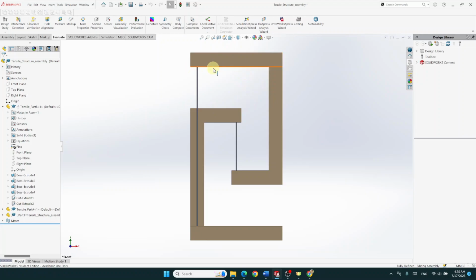And show me the weight, and show me some equation of moment, like call this one A, the weight at G, this point at B. Any other point maybe at C. Show me the different equations of moment and how they could balance each other. What happens if G, the center of gravity, is on that side? What happens if G is on that side? Will that work or not? Okay, so I'll let you work on that.